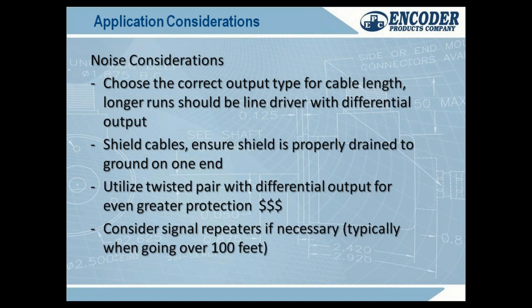But honestly, 95% of the problems I see in the field are that the encoder's not properly grounded. A lot of people don't realize that when they use a bore sleeve and a through bore or something, they're not properly grounding to the shaft. That spring spacer mount, we actually ship it with an insulated bushing. They're not grounded through the spring spacer that mounts the housing. And they say, well, I didn't want to hook up the shield because I would have created an antenna loop, and I go there with a multimeter and it's floating. It's not connected anywhere else. So you want to make sure that there is a clear drain